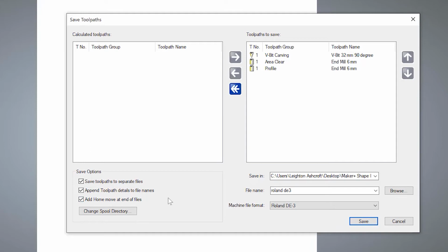Now, you could have this set to be at the back of the machine, and then the program would automatically go to the back of the machine once you finish cutting, so you can unload your material. Okay, you just need to set that up in the toolpath. So maybe you would set it to be maybe negative 48 inches by 48 inches, and it would go 4 foot by 4 foot to the back of the machine.